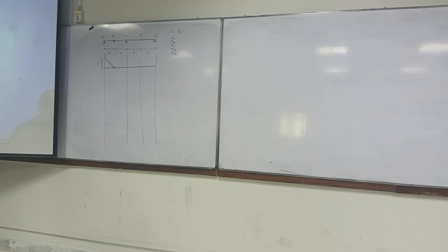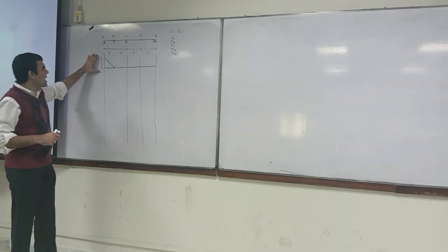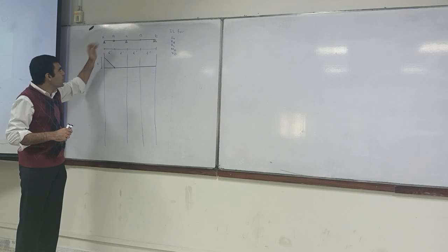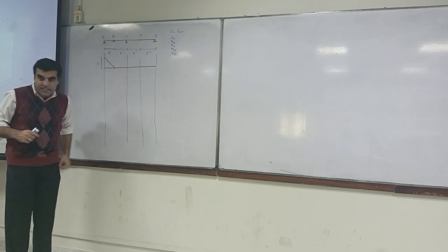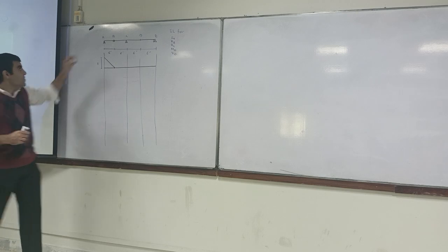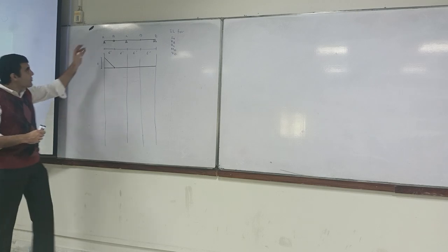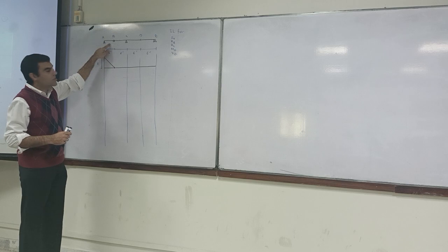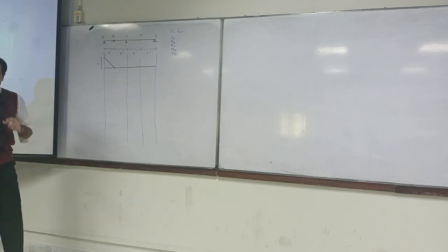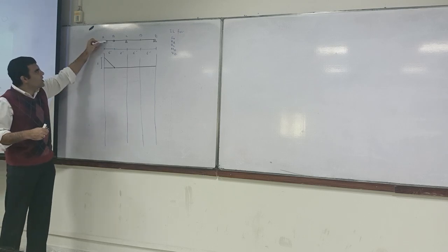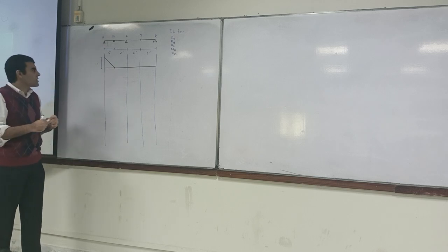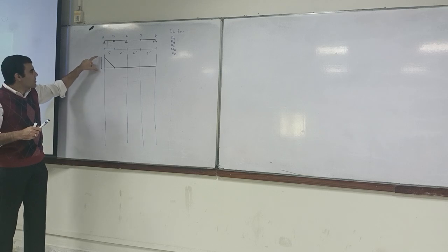Do you understand my point? Yes, it's making sense. So this is for RA. Yes, it does make sense structural analysis wise. Why? Because if we place the load in this location, this link will become active and it will start transferring the load to point A. But if you keep on moving it and place it anywhere in the other location, then this place won't be loaded. Another thing is that normally the facade is overhung from the top, but that's a different thing.